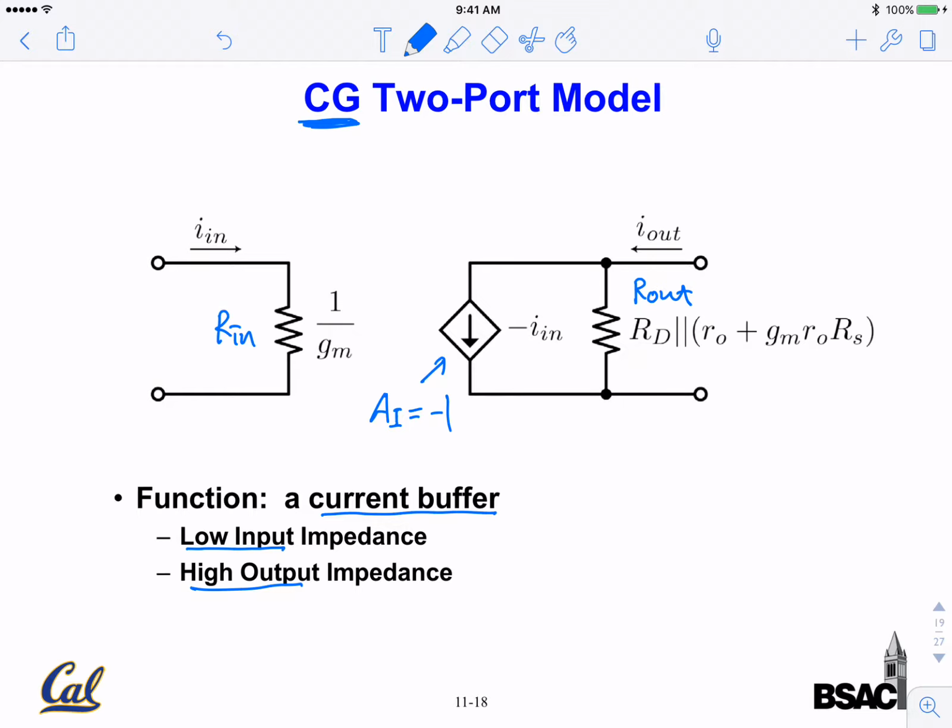It's very commonly used. What is the common value for the saturation current of the transistor? You can think roughly on the order of a fraction of a milliamp. So IDS, for a discrete transistor like you are using in your lab, is typically a milliamp. For integrated circuits, they are typically smaller, maybe 0.1 milliamp to 0.5 milliamp.